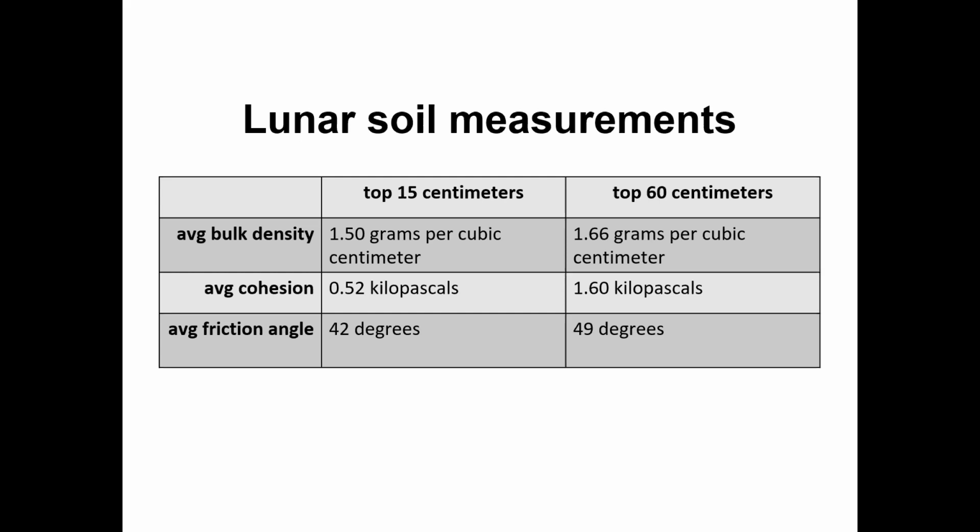The mechanical properties of lunar soil are remarkably similar to those of terrestrial granular soils of comparable gradation, even though the chemical composition of the two soil types is not the same. According to all the testing we've performed, the mechanical behavior of lunar soil appears to be dominated by the particle size, the distribution, the particle shape, and the packing characteristics.